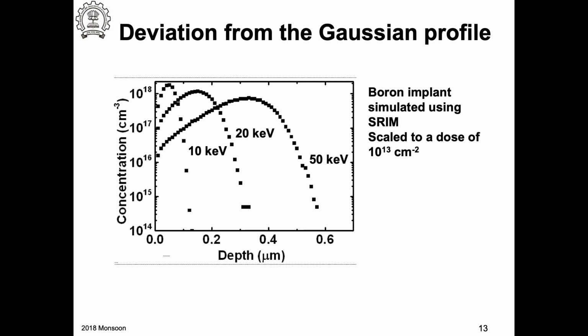So now, how do I model this? If I want to simulate a MOSFET, I really would like to get realistic doping profiles, because doping profiles can influence the device characteristics. So if I want to do the simulation, I would really like to get the exact doping profiles in my simulation structure as what is there in my device.